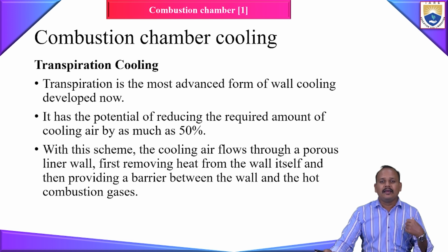Let's say previously we needed 10 kg per second of air for cooling a combustion chamber. When we use transpiration cooling, you need only 5 kg per second. So you can see how effective transpiration cooling is.